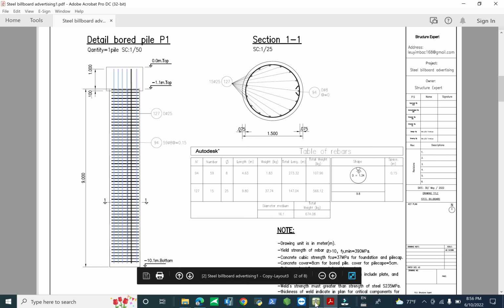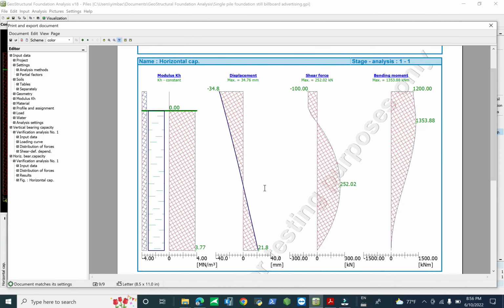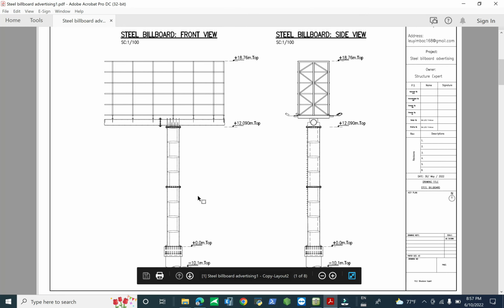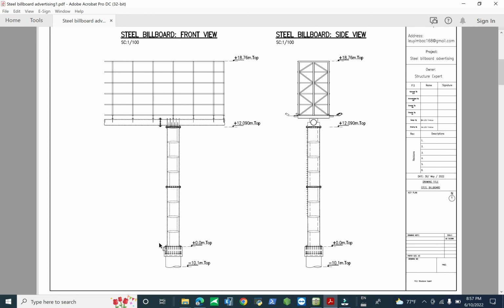You can check both software. In this case we will focus on the foundation analysis software, and we will be concerned about displacement. You cannot ignore displacement. We have displacement at the foundation, and another displacement at the upper structure. The upper structure also has its own deflection. When we design, we consider it a fixed base, with no deflection at the base.